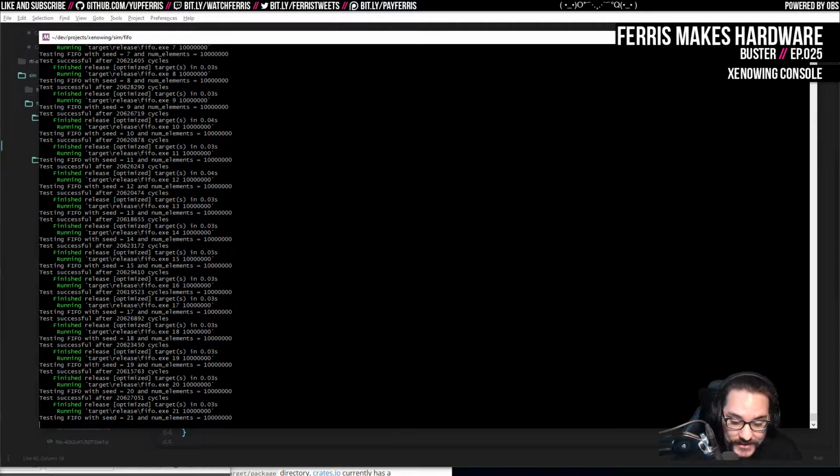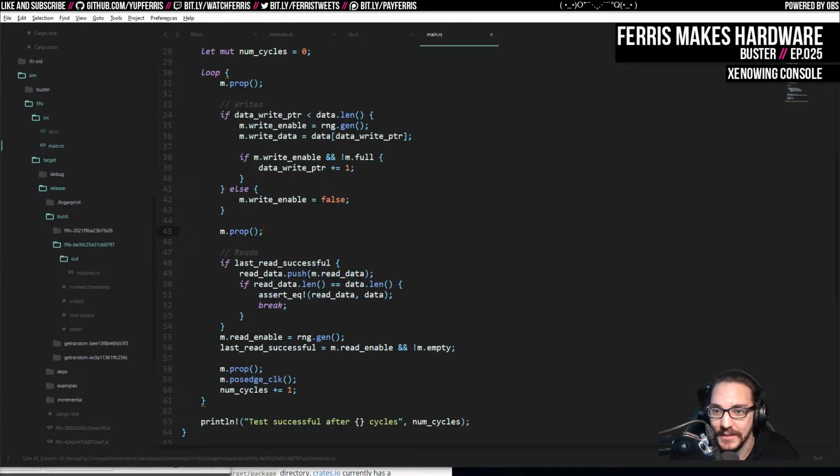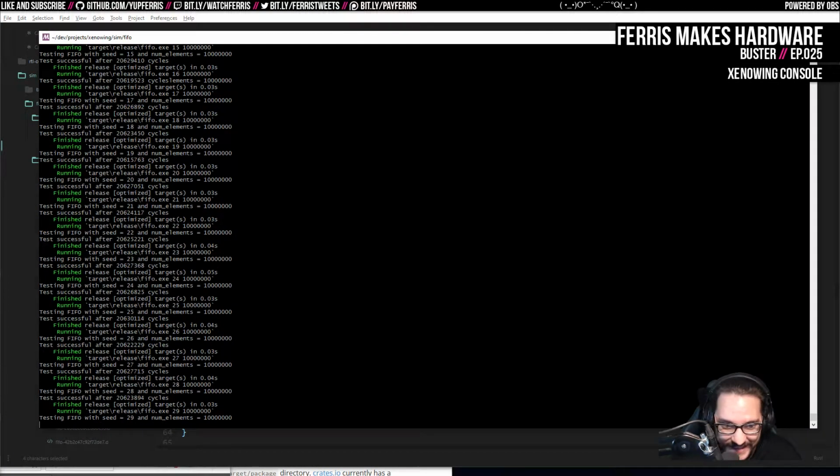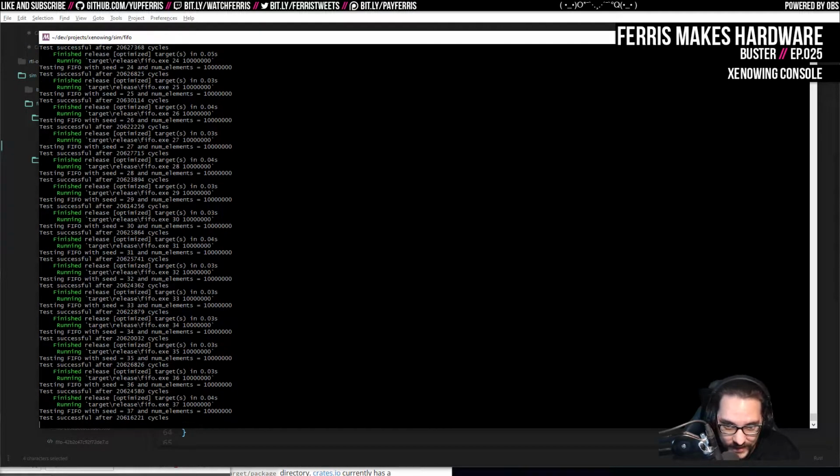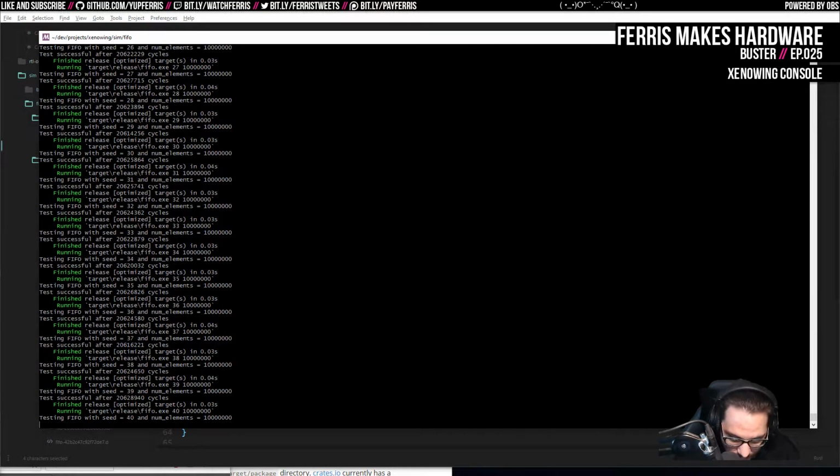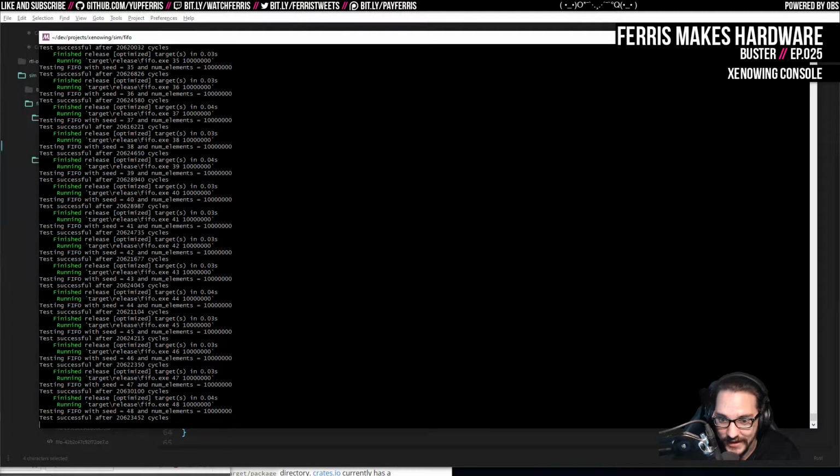But this is great. I think this is a great way to fix this test, because now, again, yeah, you guys get it. I think this makes sense. So I'm pretty happy with that fix. I don't think it's very visible in this test, but it should allow us, in the case where the Fifo is initially empty, to get data out of it a cycle sooner than would otherwise be possible.